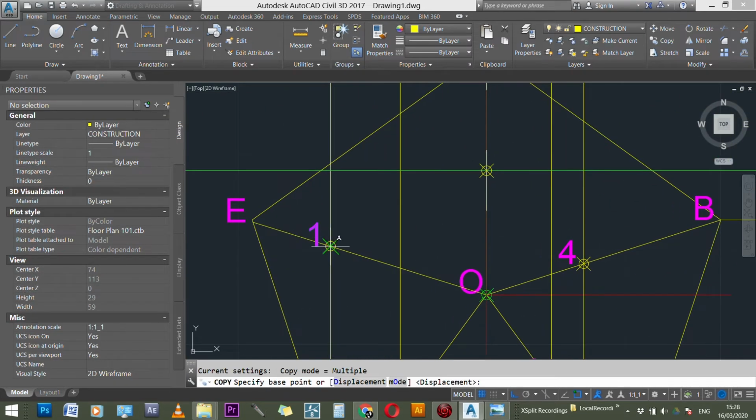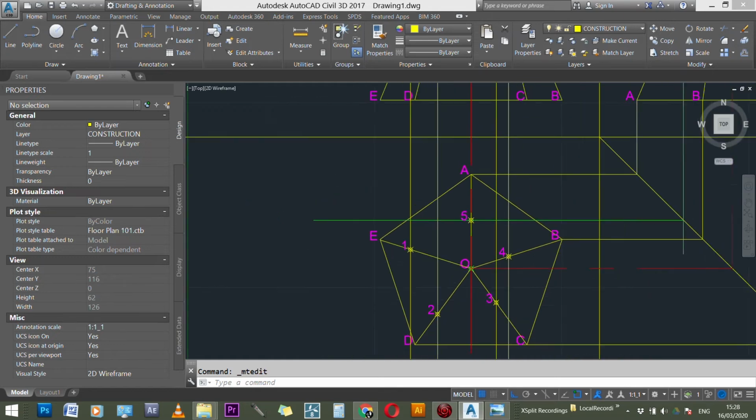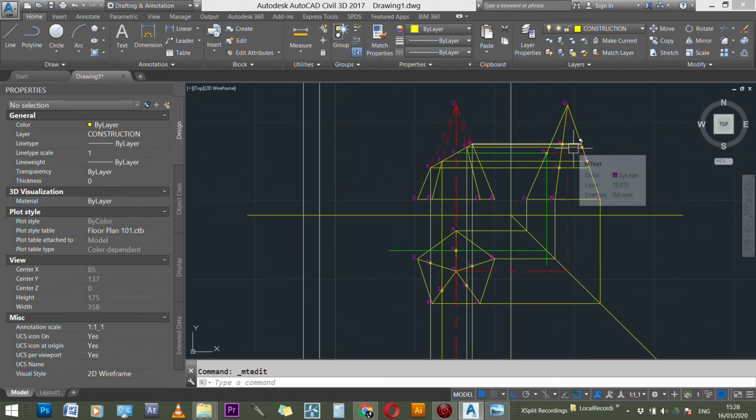So it's a little trick there: you find all 4 points, but the 5th point you need to actually create the side elevation, then project that point down through the information line, turn the 90 degree corner at the information line, and then project that line back to the plan. So that's what we have done so far.